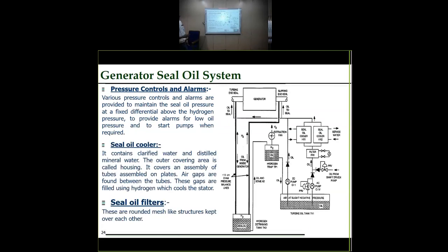There will be various control systems, that is oil pressure will be regulated, oil temperature will be regulated. There are two service coolers, so that we can bypass one if there is a problem with one cooler here. So there is a filter. In any filter which we are using, we must have a differential pressure switch to measure the differential pressure. If the filter is clogged, then we have to clean the filter.